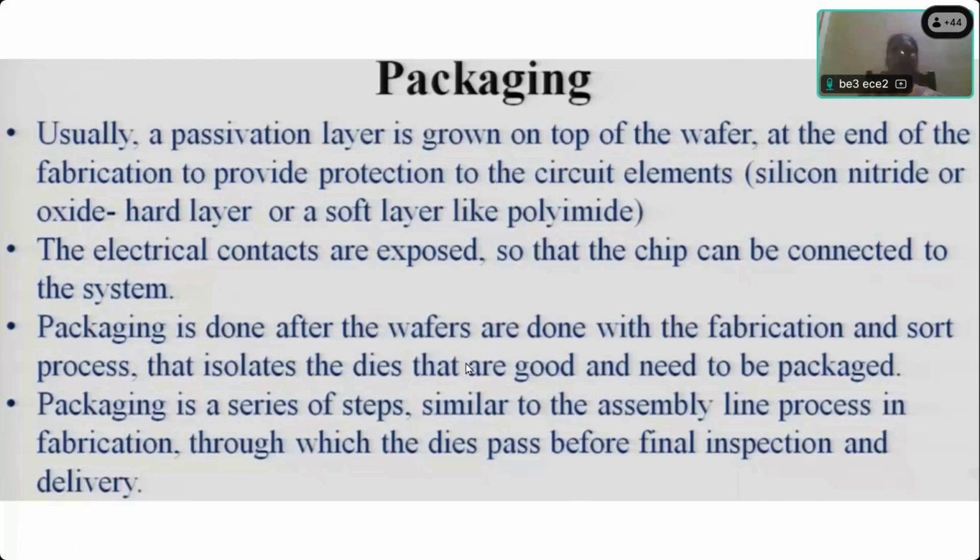So a bad die will go again for IC fabrication for minute corrections, and if it is completely out of control, with more damage or more defects, those dies should be thrown out. Only good dies we have to take for further process, then only we do packaging. Simply taking all the dies and doing packaging is a waste of time and resources.